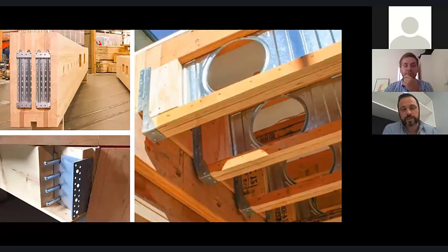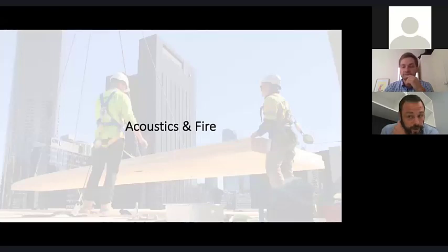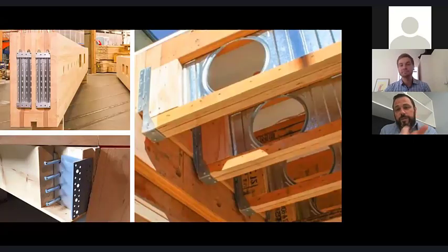Yeah, and when you have a panelised solution, your robustness is vastly simplified. It's quite economical to go down like a notional removal of elements path. You've got a lot of alternate load paths in those systems, and a lot of connections that are tying all the elements together. And your service integration is pretty good there as well. If you just go back, Nath, you can see with that tech beam or a posi strut or something, you have space to run services within that construction depth, which, running a CLT panel, you don't. You need to run that underneath. Yeah.